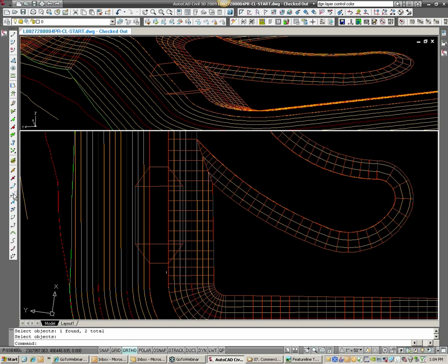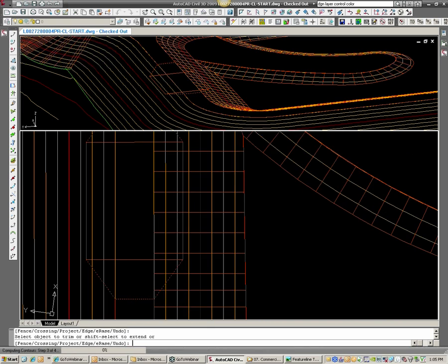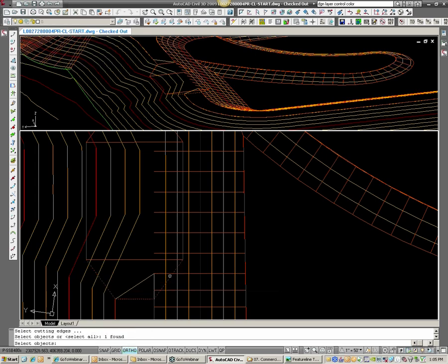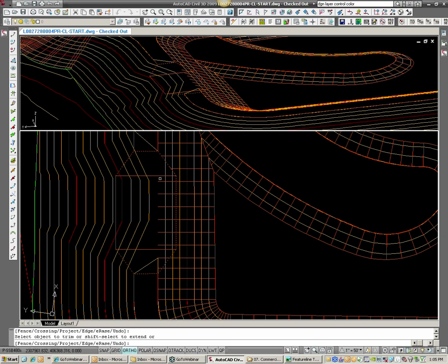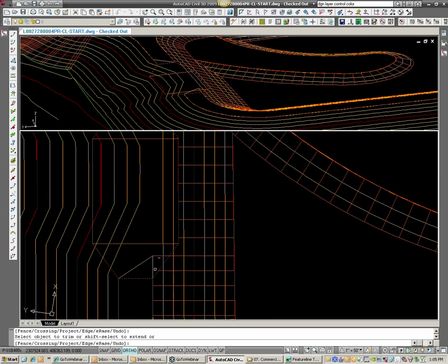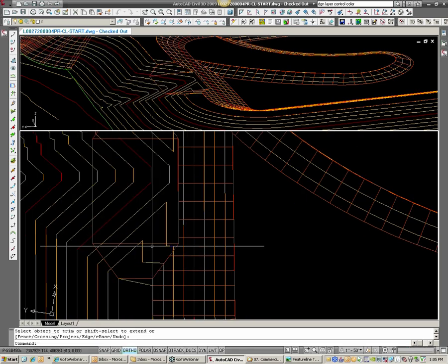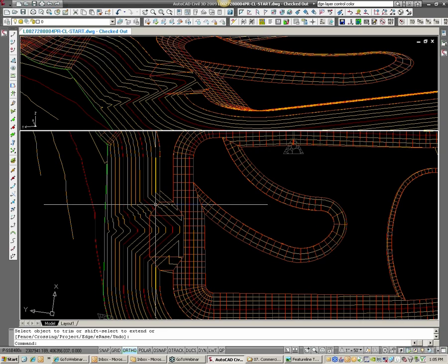Essentially here it's just trimming stuff out. So I'm going to go ahead and use my feature line trim command, trim out the top of the walls here. Actually, those are 3D polylines for this project. And then I have all these extension lines coming up. I'm going to trim those out as well. And you can see it's getting all ugly looking, and you're thinking, oh, you're losing faith on me. But all I need to do is add this geometry into my surface.